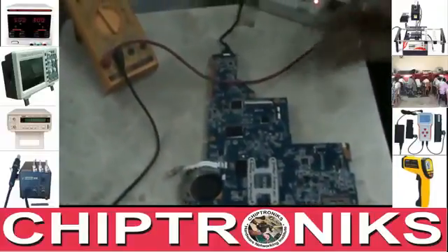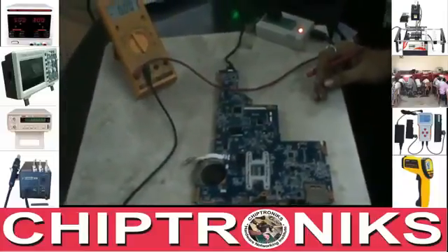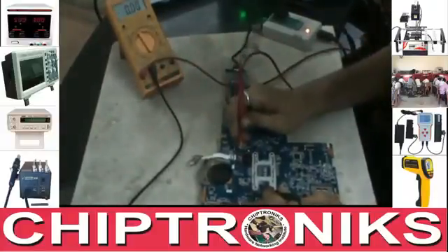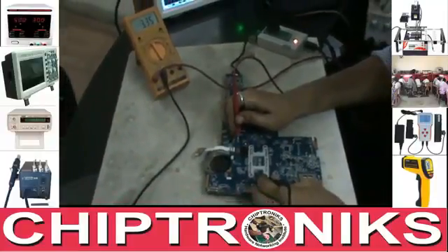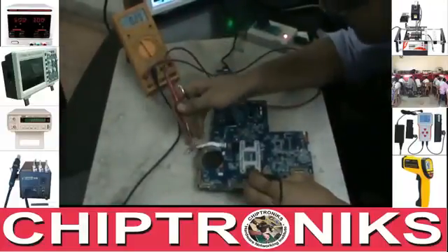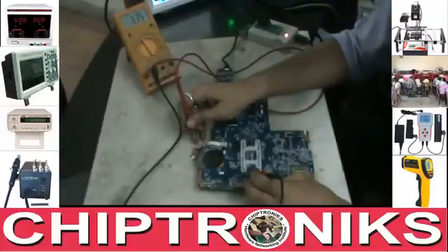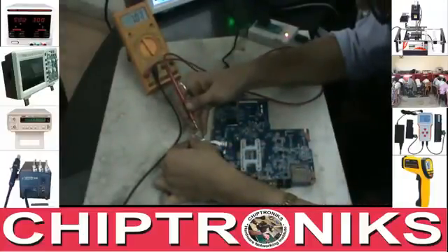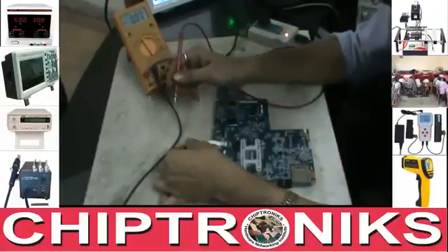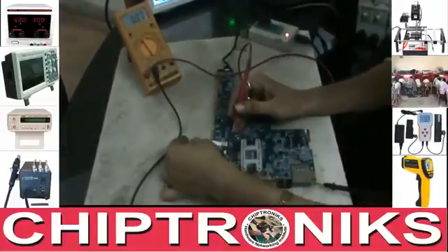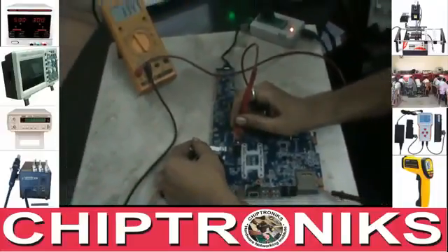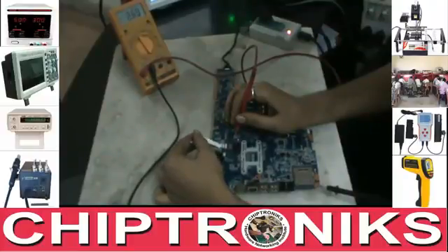Look, this laptop motherboard is in dead condition. I'll show you here. Here we get voltages on the on/off trigger switch. Look, 3.3 volt I get here, but when I short these legs, the motherboard does not turn on. Now I'll show you. I press the trigger, it gets triggered but does not turn on. 0. After the trigger, 0 or again 3.3 volt.